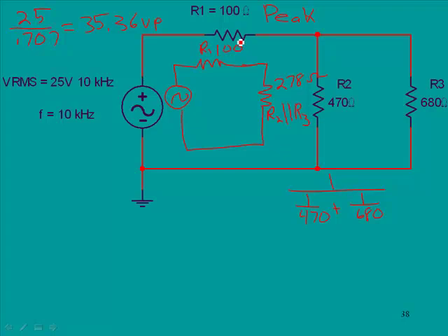And this would be our equivalent simplified circuit. One of the goals here is to calculate all the currents in these circuits, so we need to know what the voltage drops are at each point in order to do that. Given these two values, there's a number of ways we could do this. We could take the total voltage divided by these two components together, get the total current, and then calculate the voltage drops.